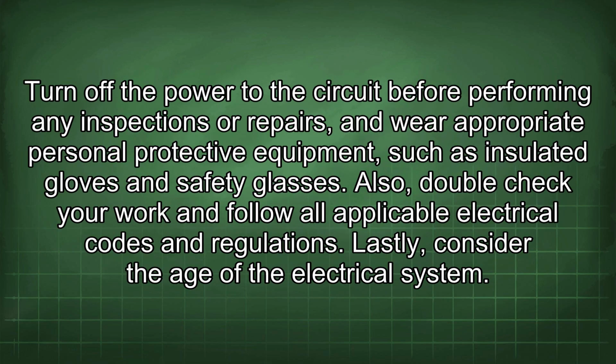Remember to always prioritize safety when working with electricity. Turn off the power to the circuit before performing any inspections or repairs, and wear appropriate personal protective equipment such as insulated gloves and safety glasses. Also, double-check your work and follow all applicable electrical codes and regulations.